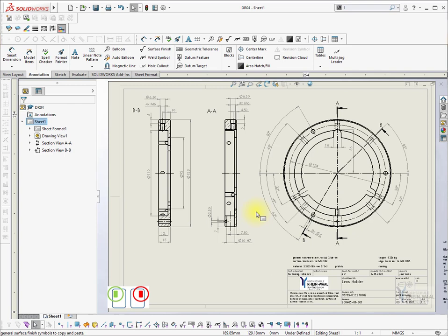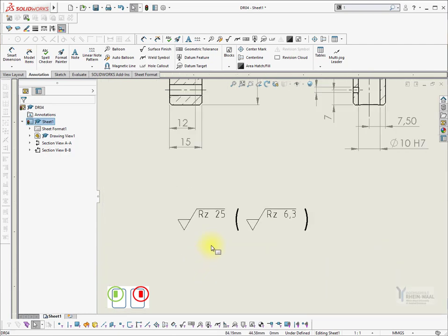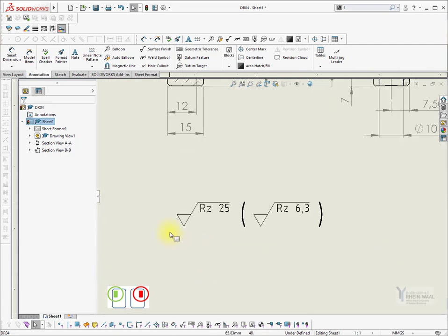From provided document general surface finish symbols to copy and paste, choose suitable combination and paste. So in general this is a surface finish which is as easy as possible for manufacturing, but can fulfill demands of parts function.